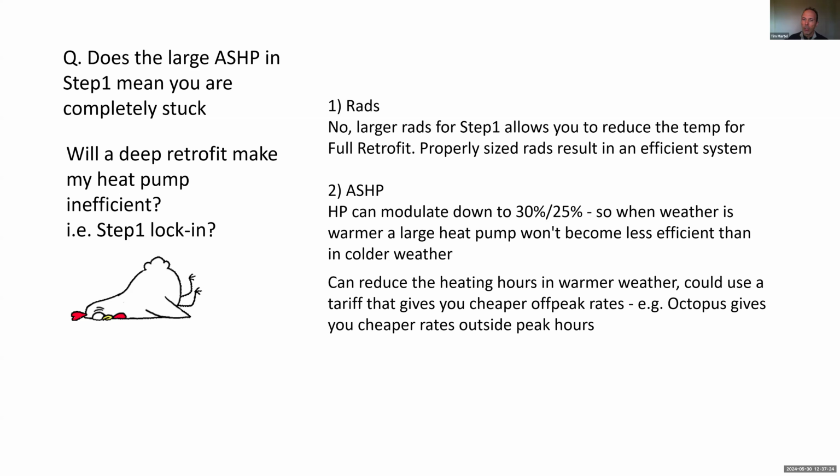And the other thing you can do is reduce the number of heating hours in warmer weather. And if you do that in a sensible way, you could shift it to the times that you have off-peak rates. So that's another advantage. So our expert, Alan Clark, considered that it's not actually a real issue having a larger air source heat pump. Obviously, it will be better in the long run, but it shouldn't stop you from doing the retrofit.